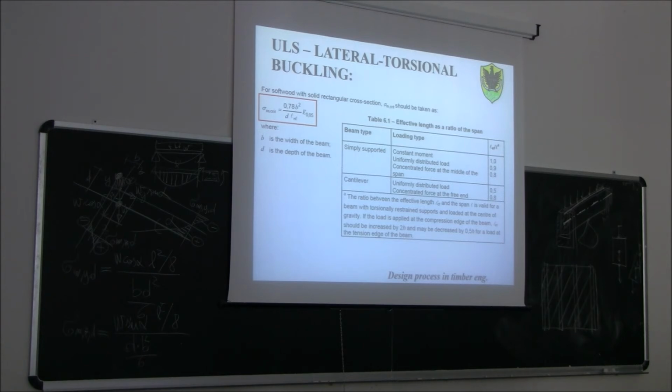The length is increased by 2h, because the load is applied to the compression edge of the beam. But here, L_ef equals 2h plus 0.9 times L.